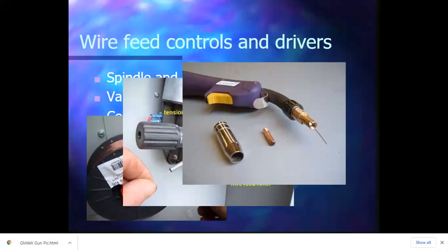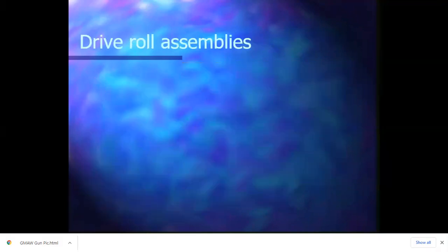There's a diffuser here. This is it here. It holds the contact tip, but it also has holes in it. There should be 4 holes around it. Those holes are for the shielding gas. So it pushes out around the end of the contact tip, fills the inside of the nozzle, comes out of the end of the nozzle, shielding your weld, giving you a nice, happy little environment, free of nitrogen, oxygen, CO2, and all those levels that we don't want. Now, CO2 isn't bad for welds. We can use it as a welding gas, but we definitely want to keep that oxygen out of our welds.